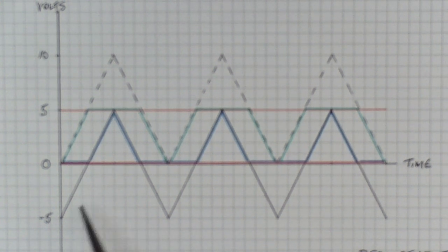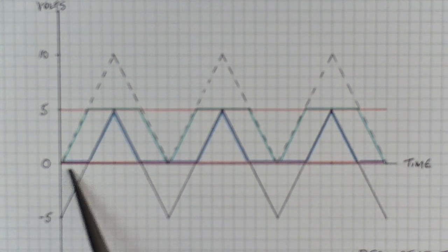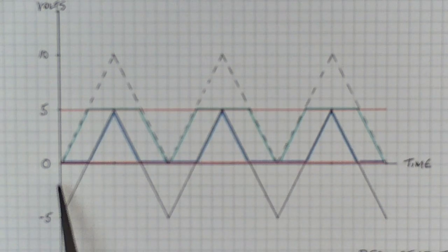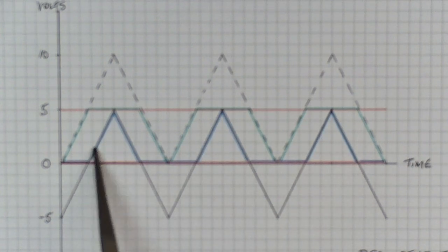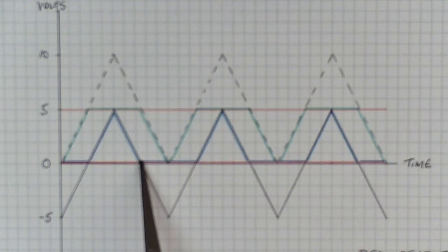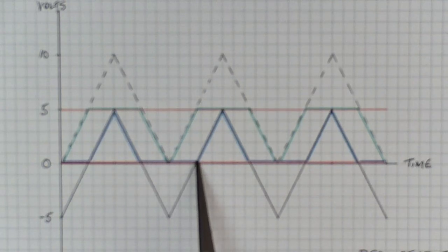So if we were to just put a normal LFO into Rorschach, for the periods where the waveform is below 0, Rorschach will effectively just be stuck at its lowest voltage, that is to say 0. So from a triangle input, we would have an attenuated triangle where for at least half the waveform, Rorschach is just stuck at 0 volts.